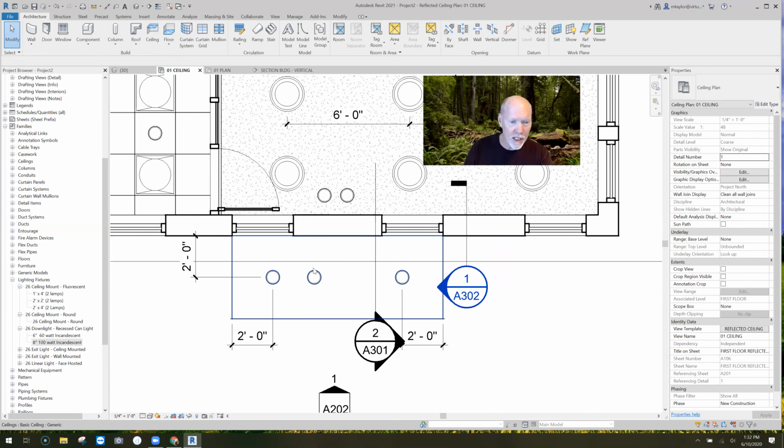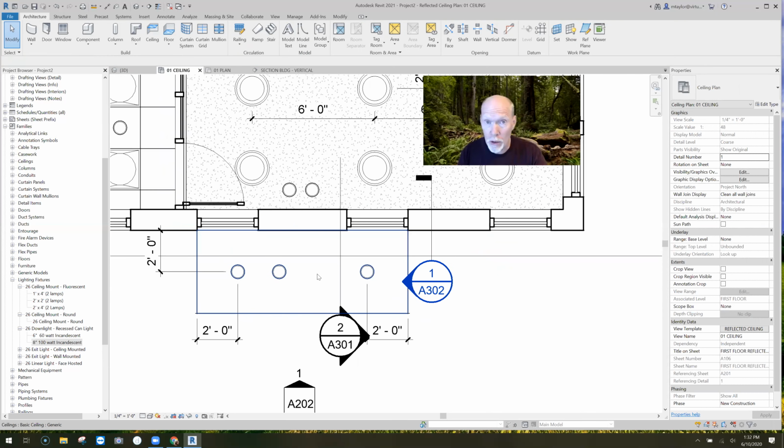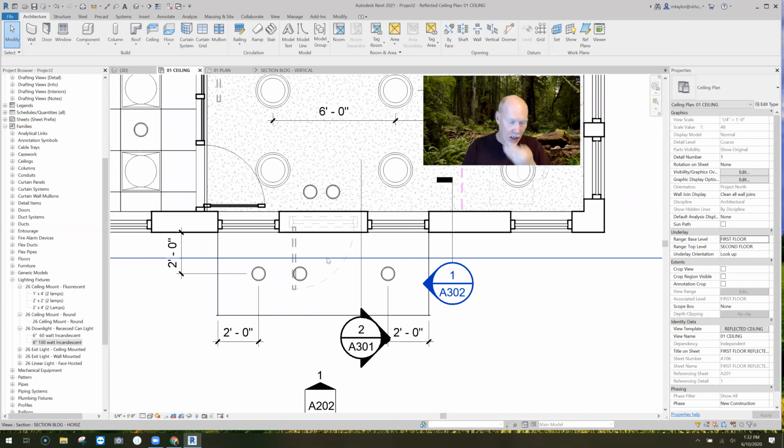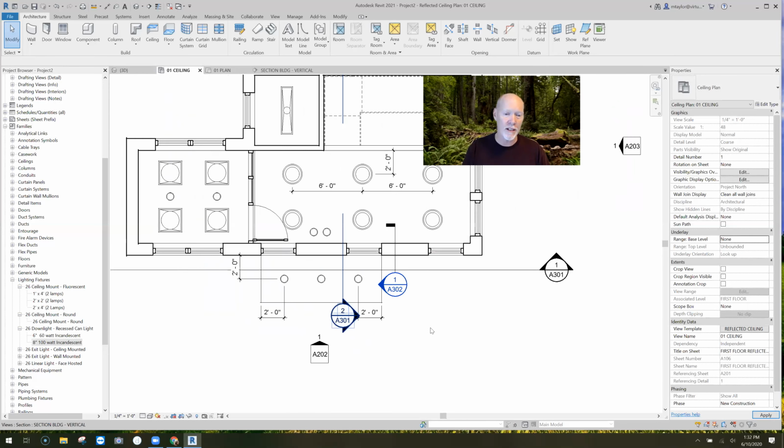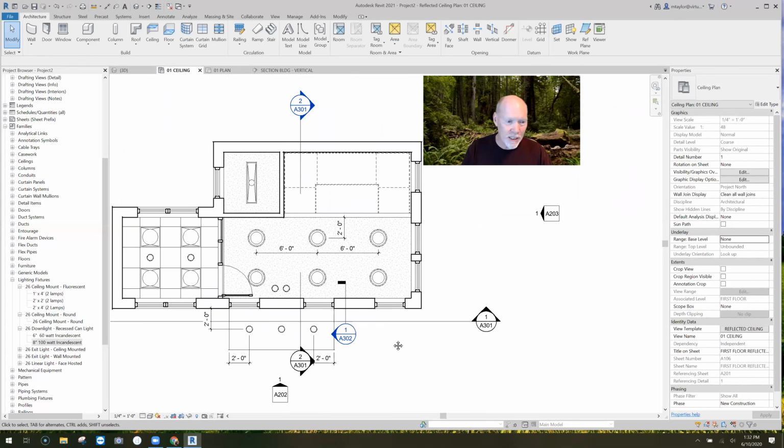Now, in this particular view, I can't see the door. So what I could do is go over to the underlay and change the underlay, the base level from none to first floor. And then I can see the door. Boom, see? You use underlays to help for alignment purposes, and then you turn the underlays off. So now that I've got it there, I can say AL, align to the center of the door, and then go turn my underlay back to none. So now I know that's centered on the door. Anyway, there's little tiny tricks like that.